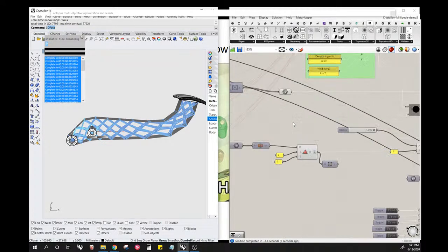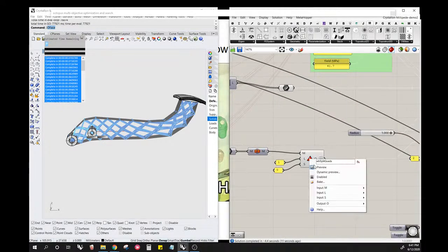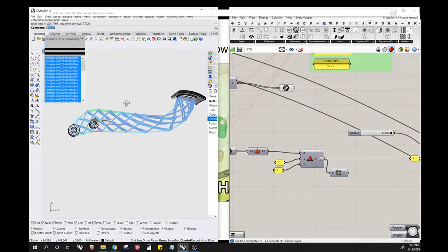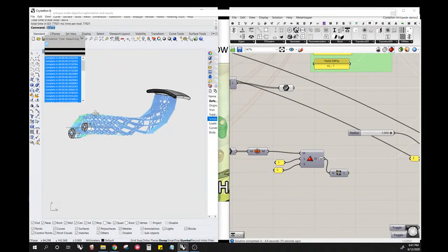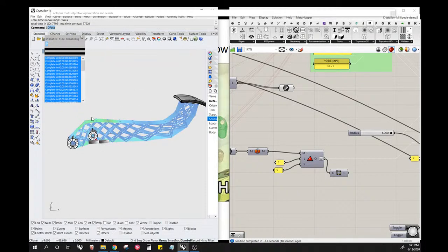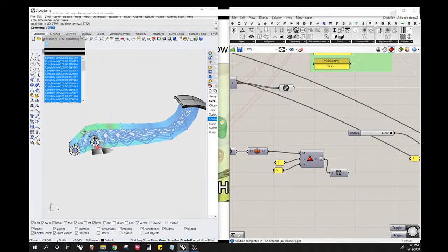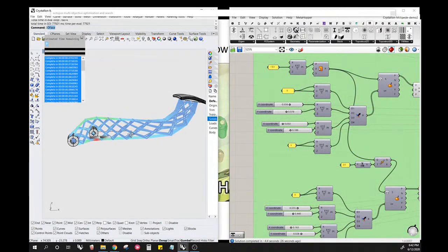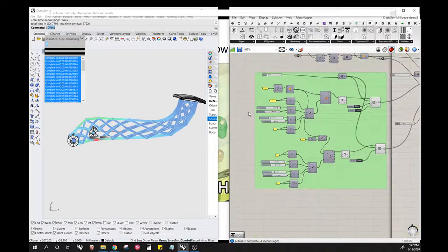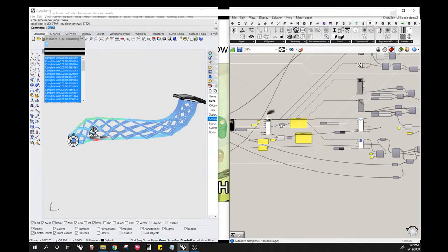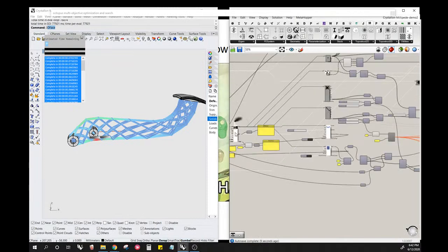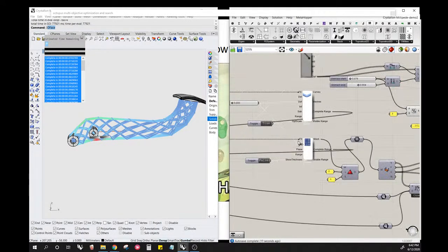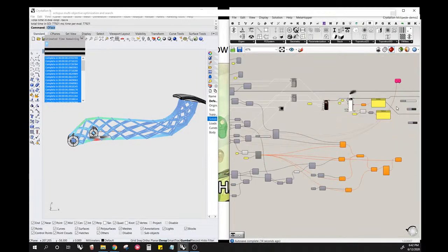So let me hide this mesh. So now we can look at the stresses. Basically we're making this brake pedal out of an internal lattice and two mesh skins on the outside. And we can change these parameters and see how that affects the strength of the structure. And then we do another beam and shell optimization, with beams and shells, and we validate those results.